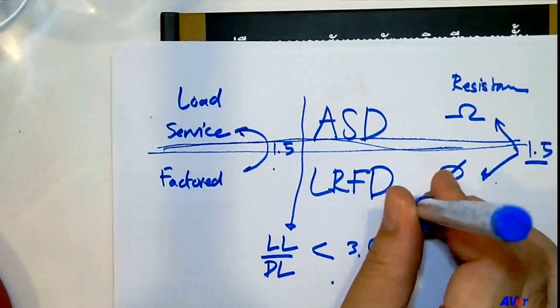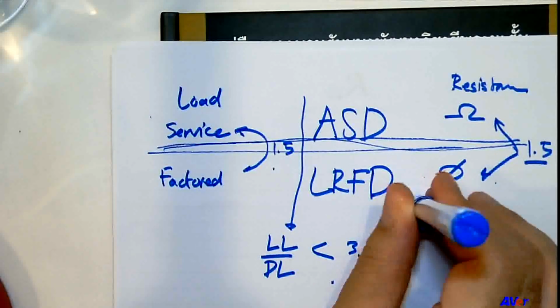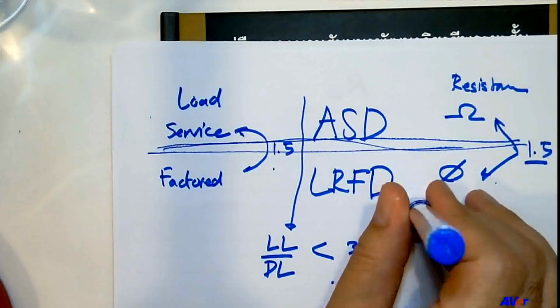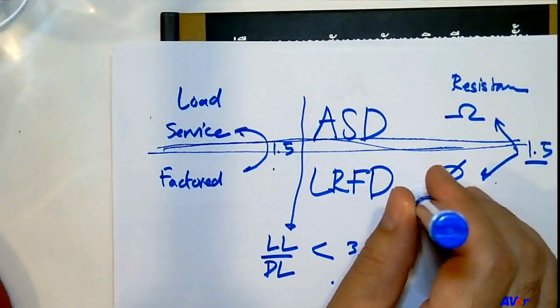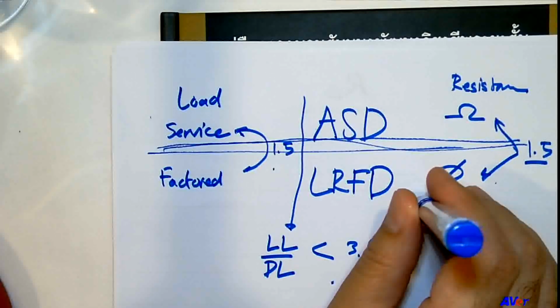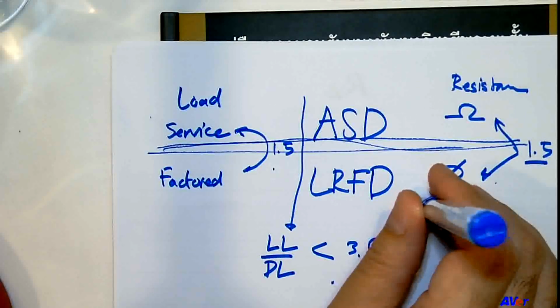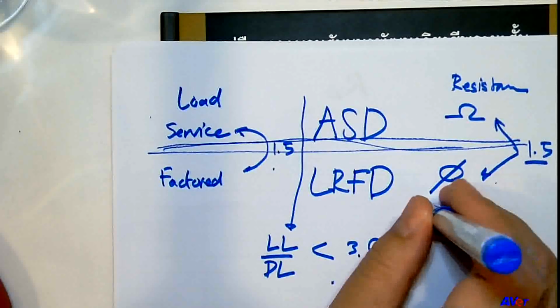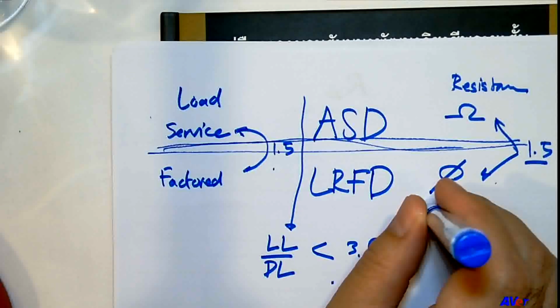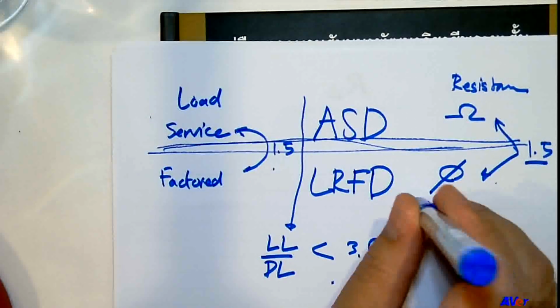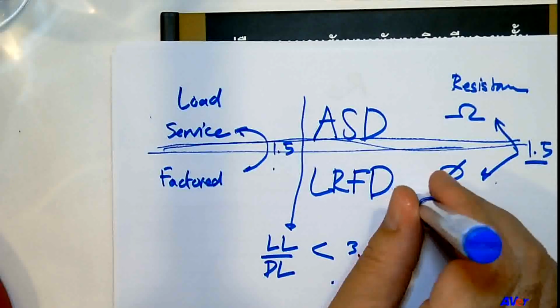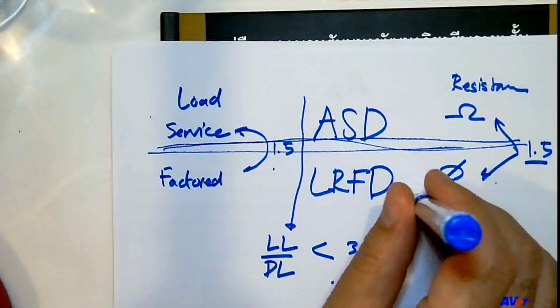And notorious is always a bad thing, right? Yeah, so some of you may already know this. If you have to handle the ultimate strength design in concrete and you have to abide by the law, you have to face that crazy 1.7 dead load plus 2 live load because it's a law. But if you read more carefully, you see that is only for concrete.